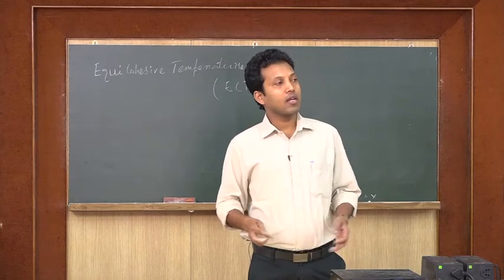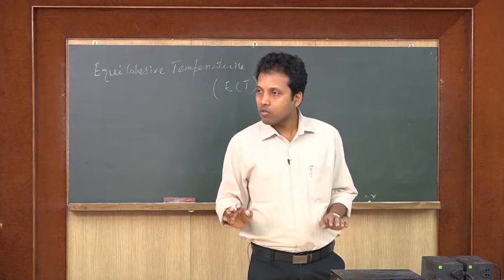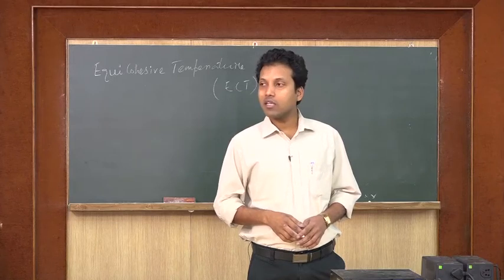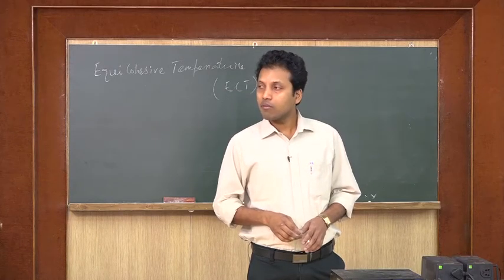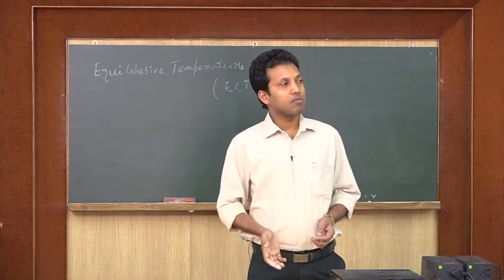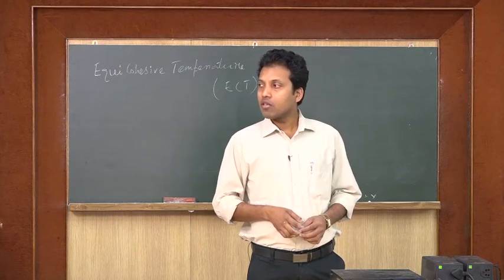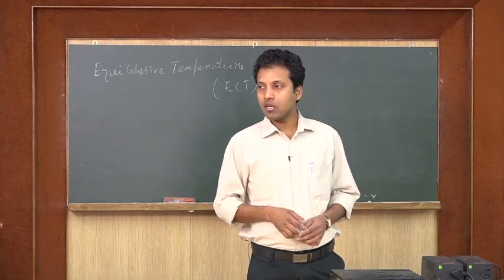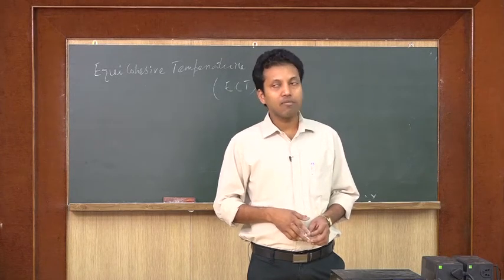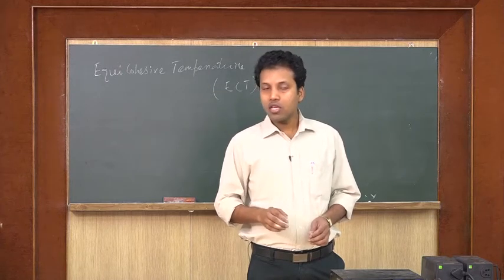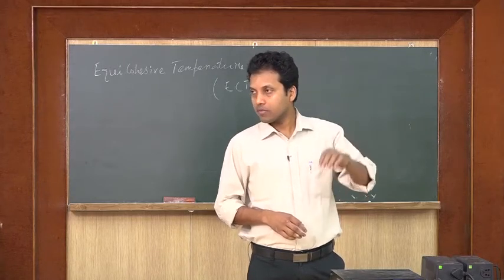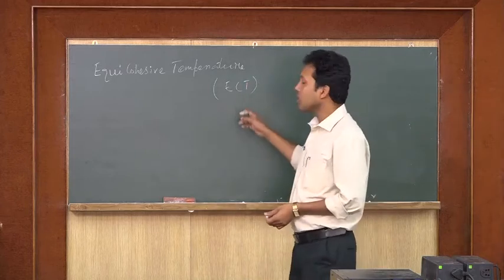Okay. So, if we are working at room temperature, or at low temperature, in that temperature range the grain boundary is stronger than the grains. But above the equicohesive temperature, the strength of the grain boundary reduces, and the grain boundary becomes weaker. As creep is a high temperature phenomenon, for many materials it is above the equicohesive temperature.